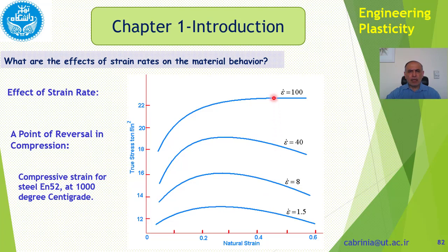But at higher strain rates, because the speed is so high, the slip systems cannot move because they need time to move. Also, the temperature, in order to influence the material, needs time, because we don't give it time in here. We increase the load so fast that these other effects cannot happen in such a short time. So because we have no time in here, these effects are negligible,